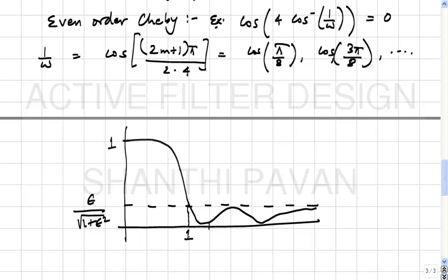But in many practical situations, the frequencies you deal with are much smaller, and at those frequencies you can still treat the circuit element as a lumped element. That's what all the networks that you've learnt are, what are called lumped elements. By lumped it means it's not distributed, all right. And also there is this common belief that RF means only very high frequencies, right? It's not necessarily true at all.